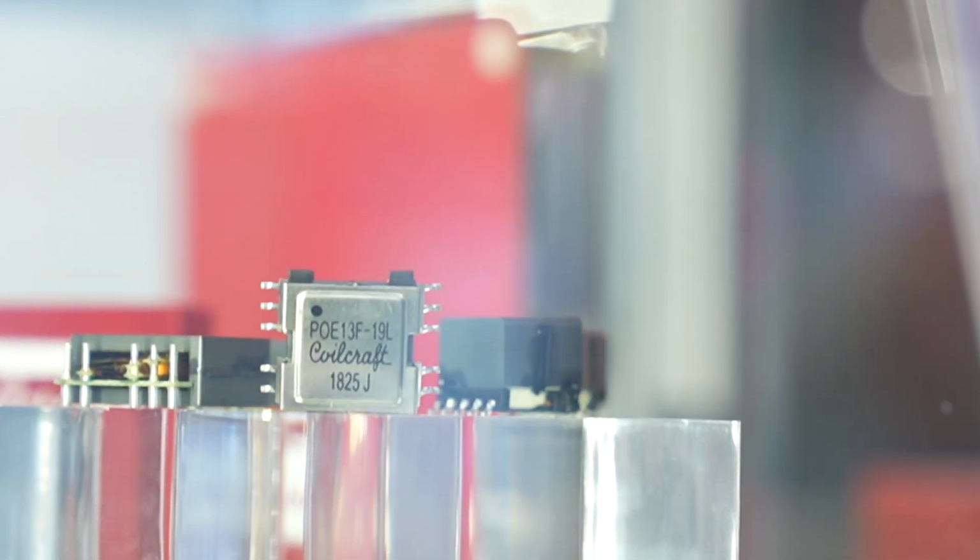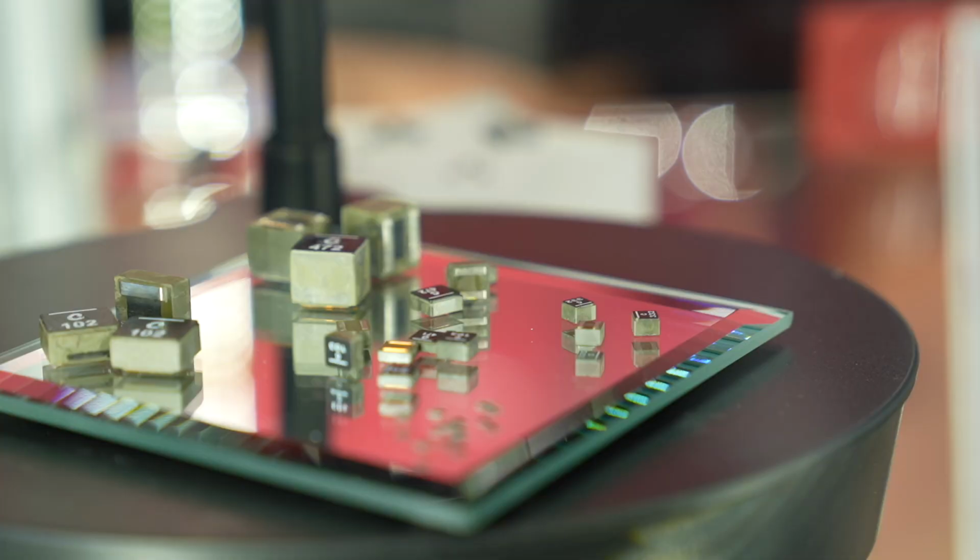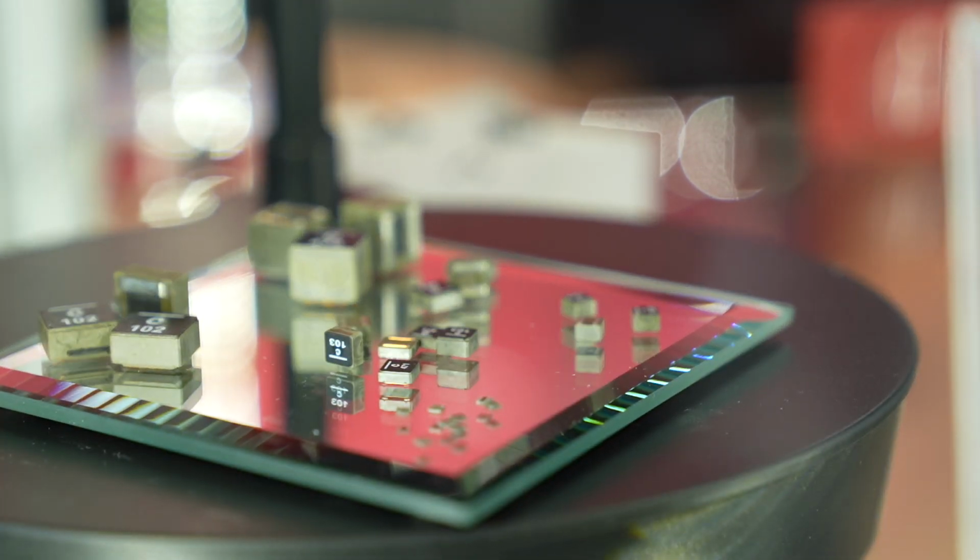We're talking about making electronics denser. Everything is closer together. One very, very important feature for inductors is how well the magnetic field is in fact shielded. And we talk a lot about what we refer to as molded power inductors now, where the windings are completely enclosed by the core material.